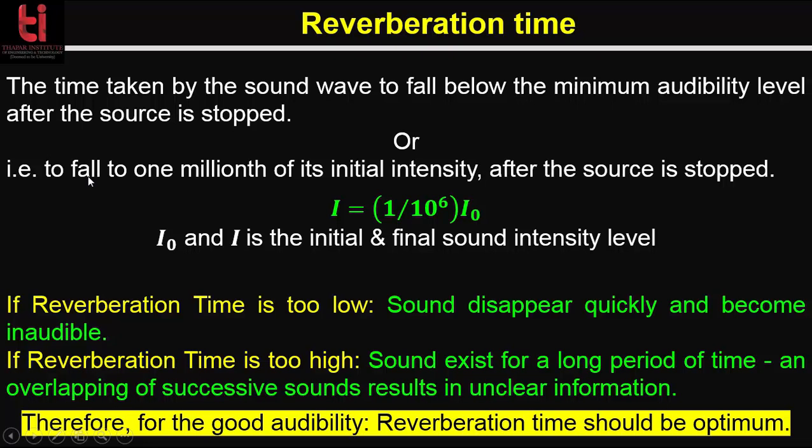Now if the reverberation time is too low, sound disappears quickly and becomes inaudible. And if the reverberation time is too high, sound exists for a long period of time and an overlapping of successive sounds results in unclear information. Therefore, for good audibility, reverberation time should be optimum.